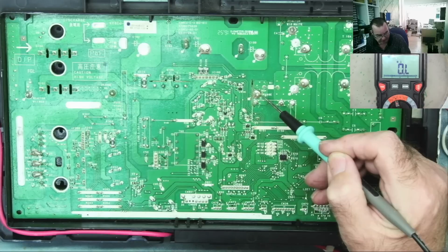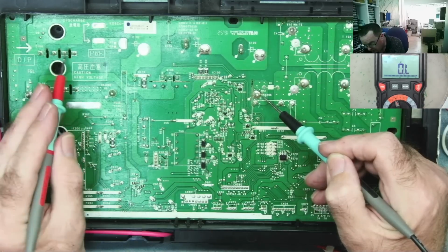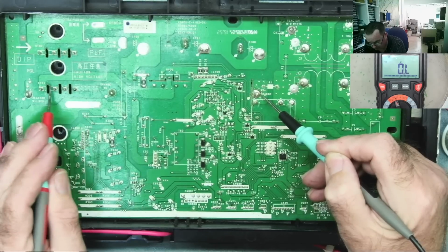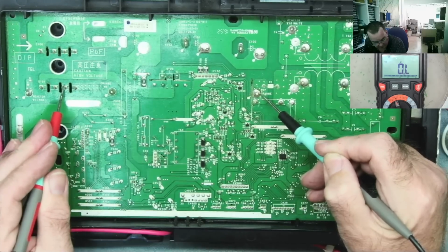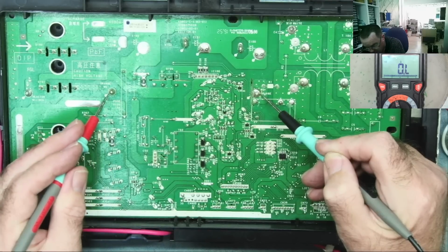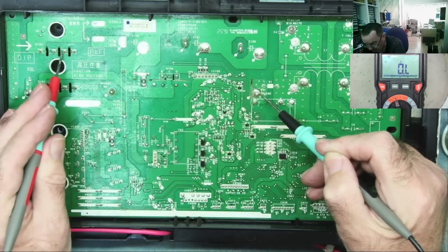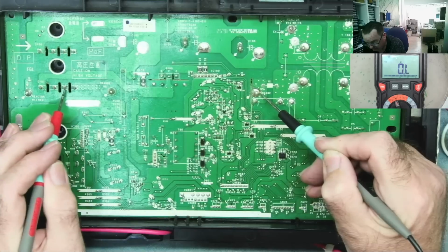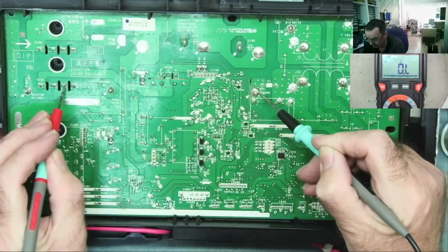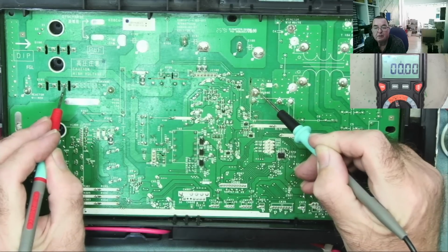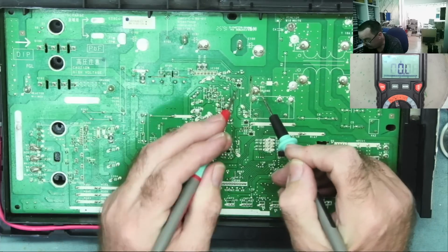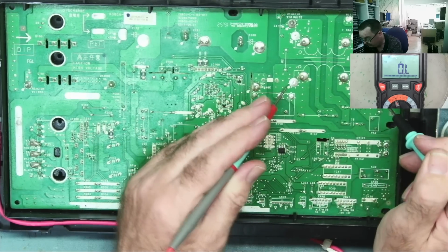So let's go back to continuity again. Yeah, that goes there. Doesn't go to this one, I'm not sure where that one's connected actually. It says orange here. Okay. Well, it certainly goes to there and there. It does go to both of them, okay? You can hear it now, bleeping. And it's reading, okay? So that's one of the AC inputs via this resistor.